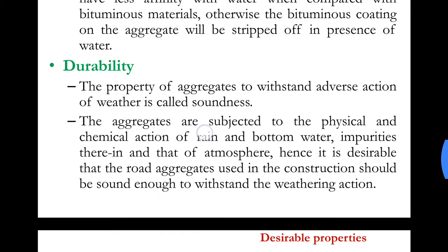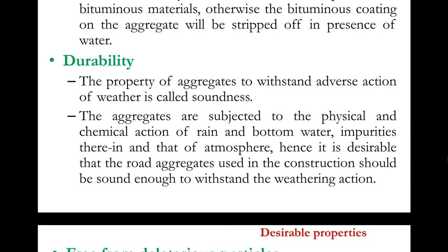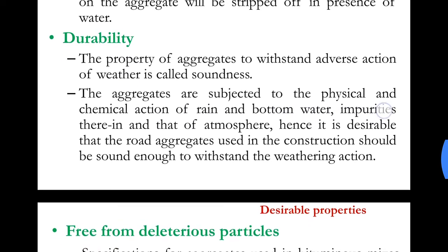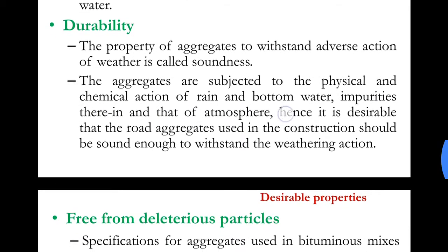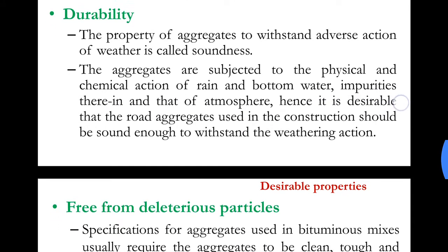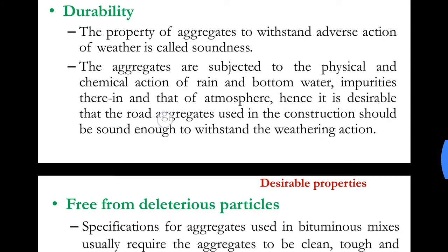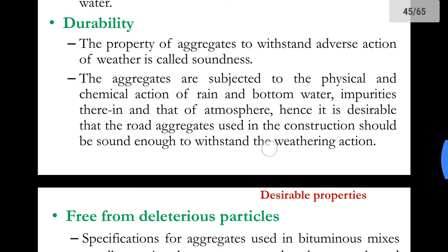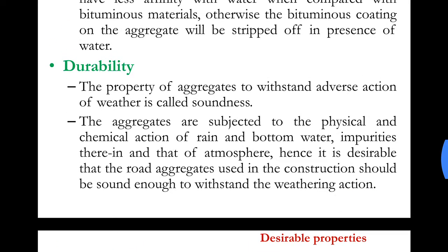The aggregates are subjected to the physical and chemical action of rain and bottom water, impurities therein and that of the atmosphere. Hence it is desirable that the road aggregates used in the construction should be sound enough to withstand the weathering action. So the resistance to weathering is known as durability, or it is also known as soundness.